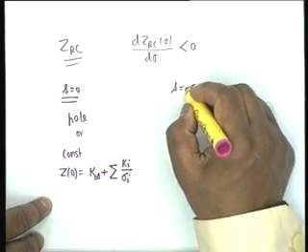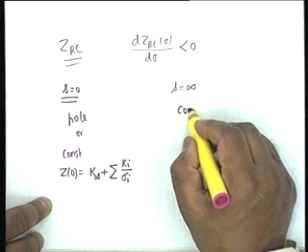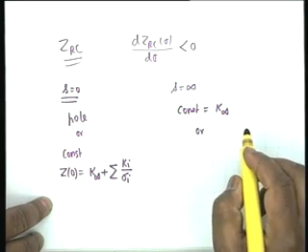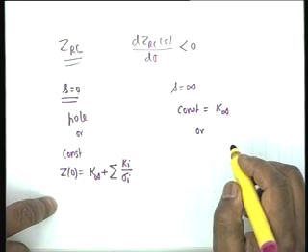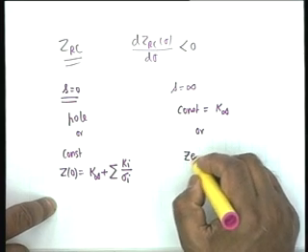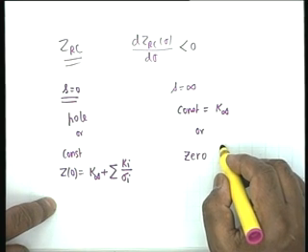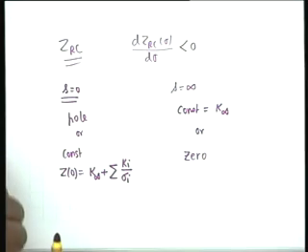At s equal to infinity, it is either a constant equal to k infinity or, what is the other possibility? 0. 0 occurs if k infinity is equal to 0, and therefore there are 4 possible combinations for an RC impedance.